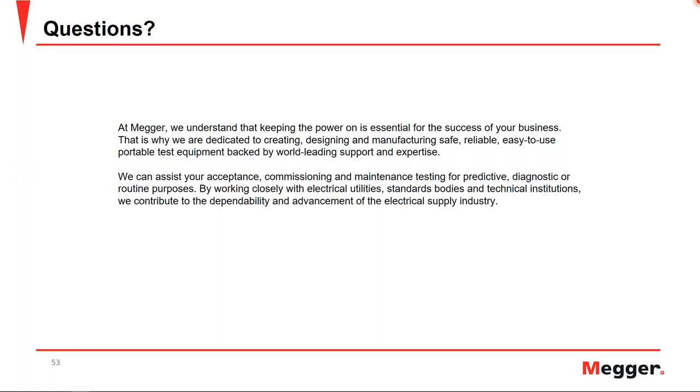If you look at the IEEE C57.152 standard, it says that power factor should not be considered for distribution class transformers. So depending upon what standard you are looking at and how much historical data you have, that would define whether you should perform the test for insulation assessment or not.